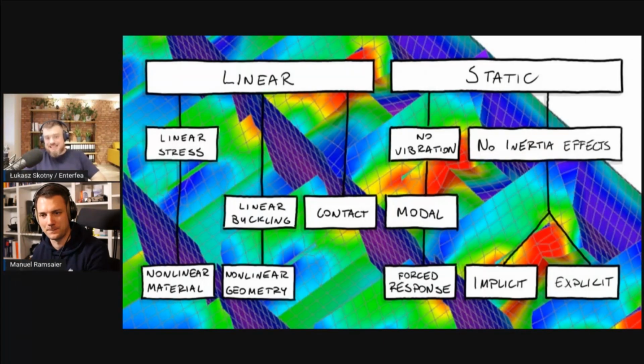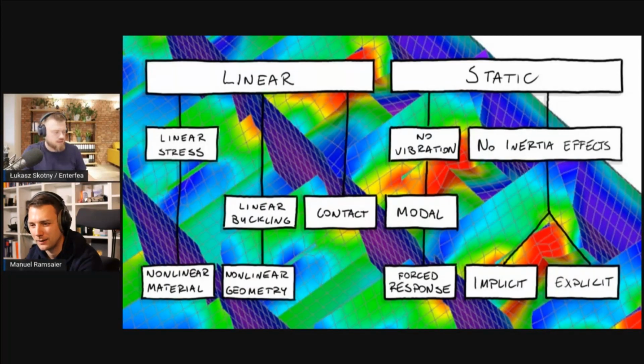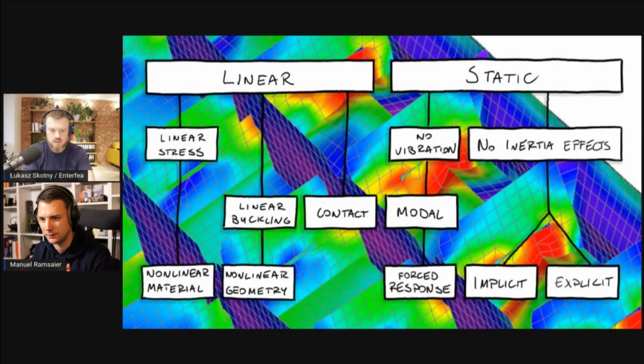Yeah. And in implicit, like the actual implicit analysis, you have a real time in real seconds, and you can play animation in real time to see how this will behave. And explicit just makes this very, very fast. Yeah, I have to learn a little bit more about those two. I'm confusing them all the time, but I thought that explicit is like you look forward in time, you have your current system, and then you just calculate gradients, and then you just go one time step further, and then just calculate it again.